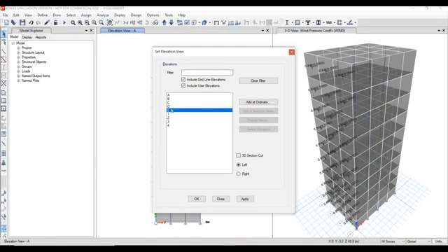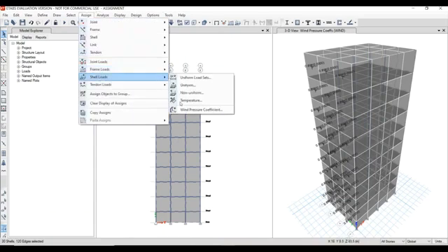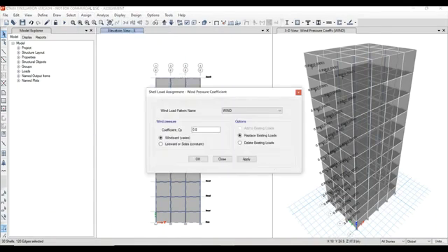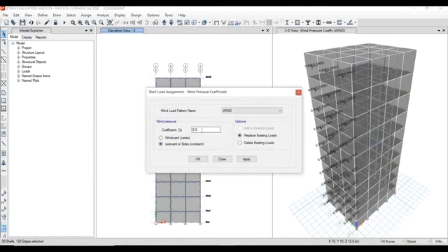Now we need to select the elevation of the last elevation so that the wind will be facing on the last face. This is the elevation E. So make sure that all stories are selected. Select every story shell. Now assign the load. Assign shell load wind pressure coefficient, which we already got, minus 0.25 in leeward direction. Click leeward, minus 0.25. Apply.